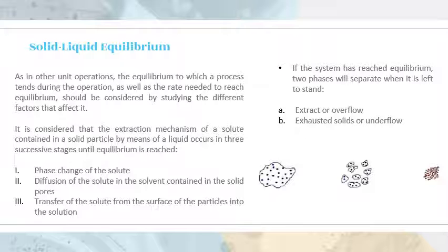In the first stage, the dissolution of the solid is considered instantaneous, so it will not influence the process. The second stage usually controls the speed of the process, as it usually proceeds slowly. To increase the overall transfer rate, various factors such as particle size, temperature, and agitation of the fluid are usually acted upon. In addition, another factor to be taken into account is the type of solvent, making it necessary to use a selective solvent with a low viscosity so that it can circulate easily.